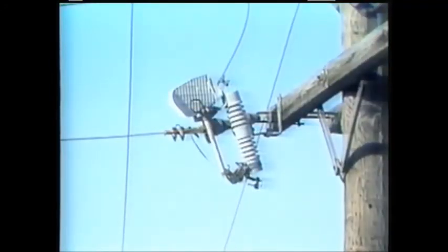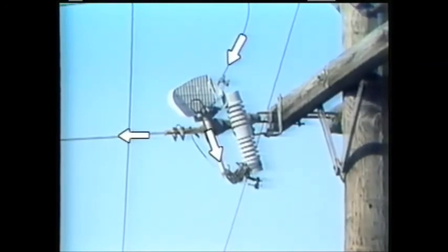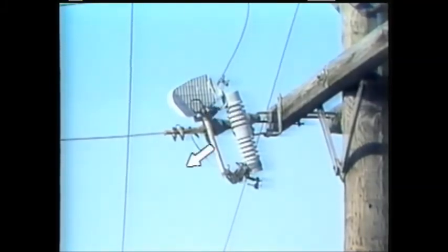This is what a typical fuse looks like. It consists of 2 contacts, one tapped off a feeder and the other connected to a lateral, and a hinged fuse. In the closed position, the fuse provides a flow path for electricity at a primary distribution voltage to flow from the feeder to the lateral. In the open position, the fuse separates from this contact and swings down, interrupting the flow of electricity to the lateral.